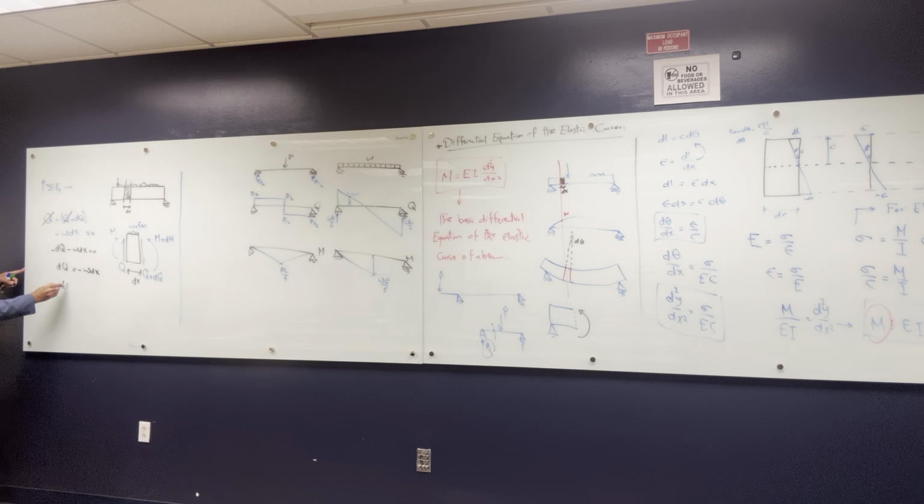So you can say that dQ/dx is equal to negative W. Or you can integrate both sides and say that Q is equal to the negative integration of W dx. That is a very important equation. Same thing we can say about the moment.